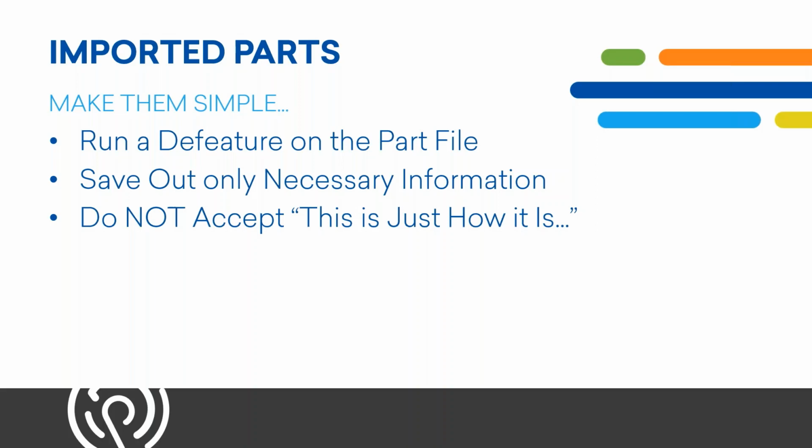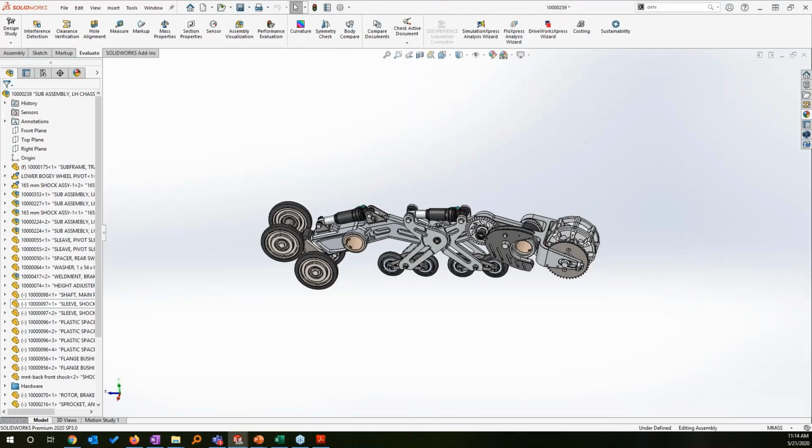There are a lot of things that we just talked about, such as whether you're mating to original planes, or whether you're using some of the object geometry. If you try and fix it later, there's a lot of things that can go wrong, and mates can break. And you'll almost train yourself not to use these efficiency techniques because it won't work. But that's really just not true in terms of the actual practicality of it. So because of that, let's switch over to SOLIDWORKS.